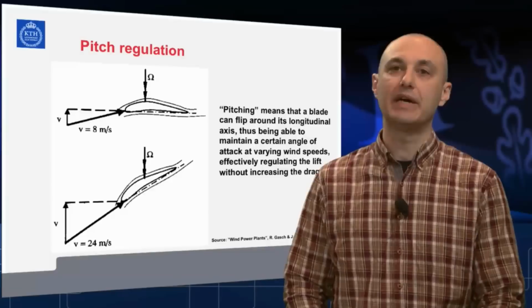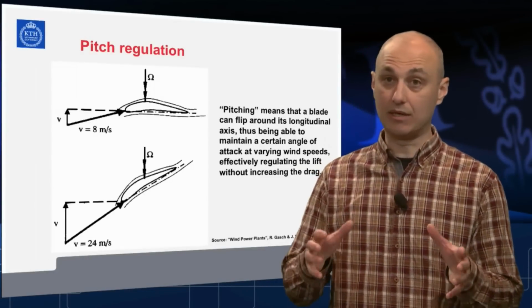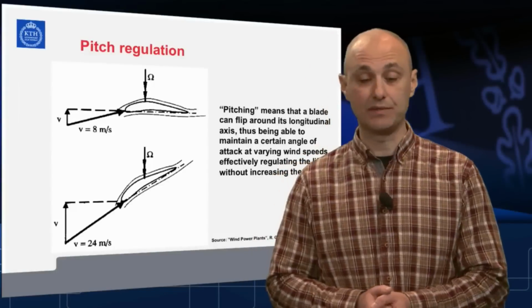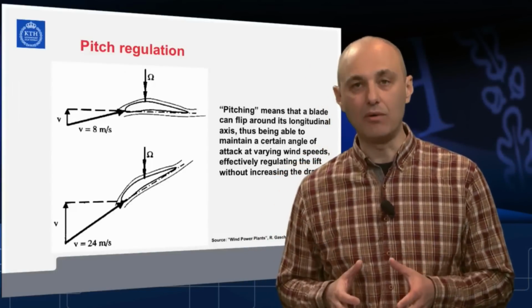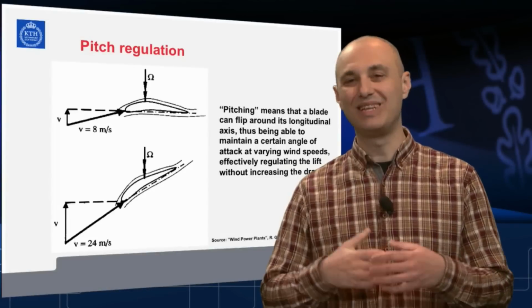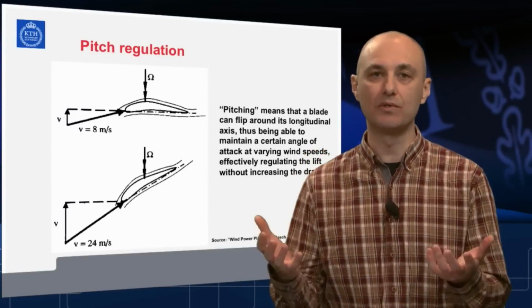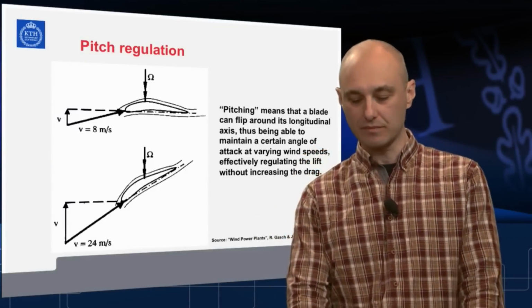So that's how people define the pitch regulation, and it is definitely the regulation of choice for modern machines. All big turbines now prefer pitching instead of using stall. Plus, stall is a bit dangerous because it increases the loads on the machine enormously.